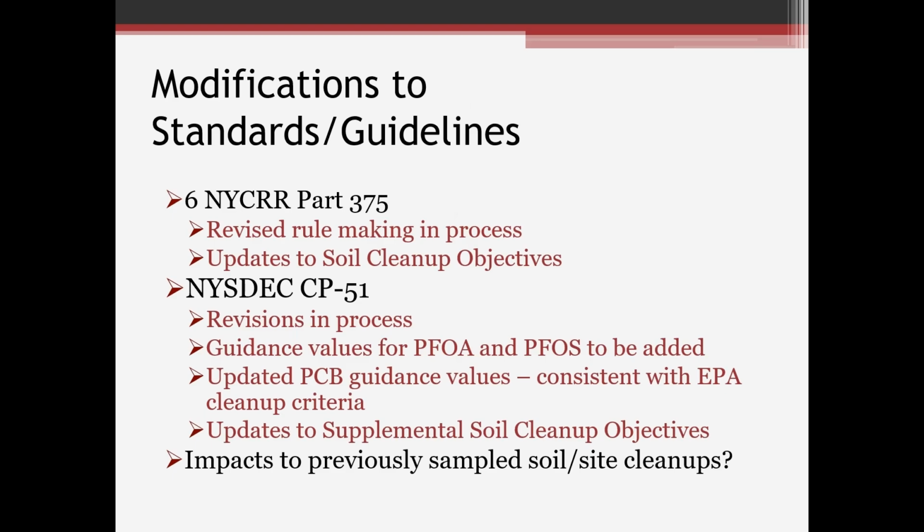All right, lastly, just to throw this out there, standards, regulations, and guidelines always tend to be updated from time to time. There are some different things ongoing. 6 NYCRR Part 375, those standards that have our soil cleanup objectives, there's a revised rulemaking in process. So some different SCOs, soil cleanup objectives, will be changed. That will affect projects in the future, which will have different regulatory soil standard values to comply with.